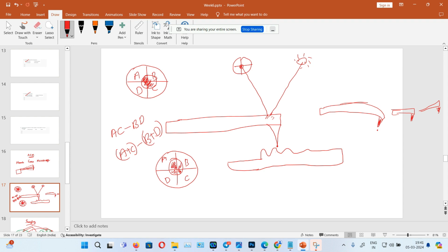Interpreting that value, you can see the position of the laser spot, and the position corresponds to the bending of the cantilever. Using the stiffness of the cantilever and other things, you can see the morphology of the specimen over which you scan. This is the basic idea of an AFM.